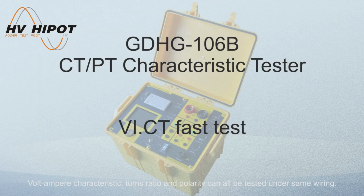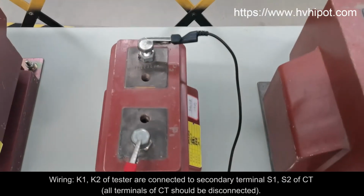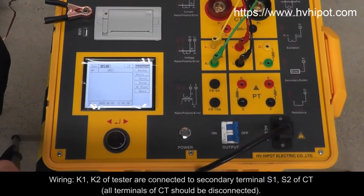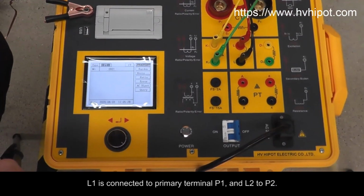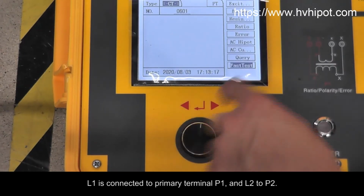Volt-ampere characteristic, turns ratio and polarity can all be tested under same wiring. K1, K2 of tester are connected to secondary terminal S1, S2 of CT. L1 is connected to primary terminal P1, and L2 to P2.